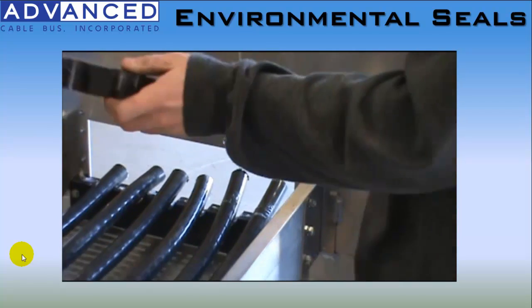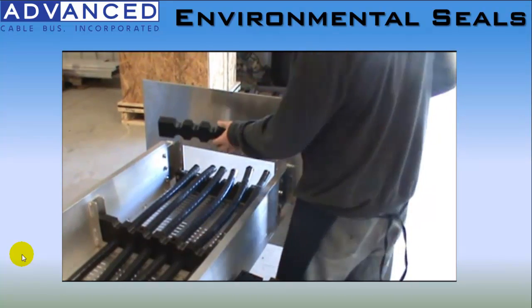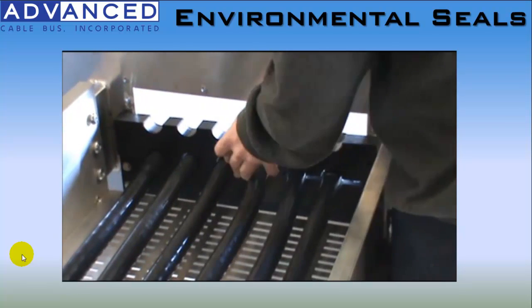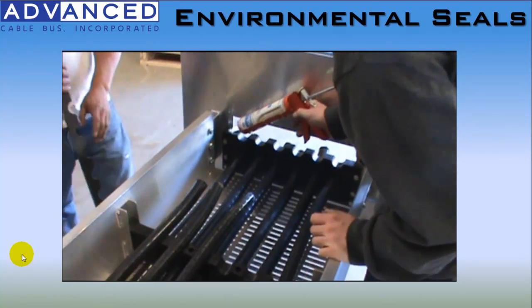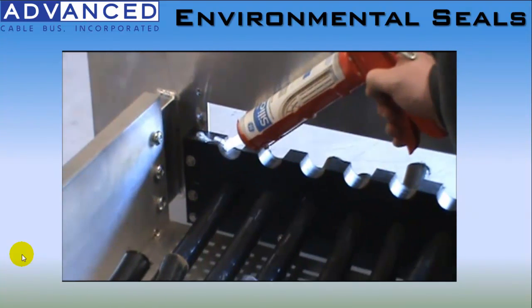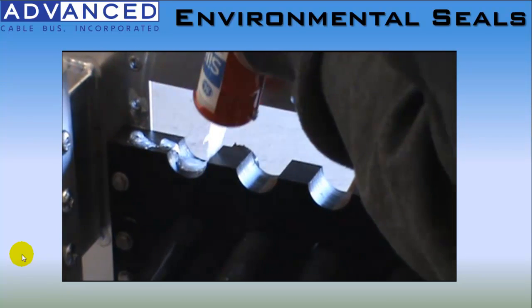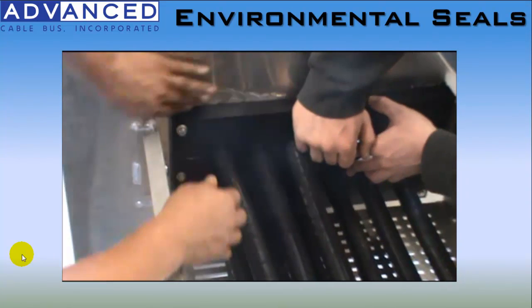Each time you add a seal block to your seal, be sure to liberally apply the silicone sealant along all the edges to ensure a watertight installation. And again, always make sure that the cables are laid flush into the groove before bolting everything into place. Once you have completed all of the seal blocks, you then tighten all the bolts down with the recommended torque.